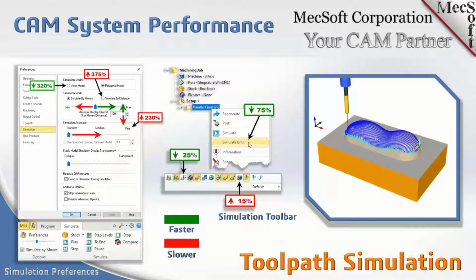You can think of a voxel model as nothing but a volume model that we create of a part file or a stock file, and that's what we use for simulation. The voxel model has restrictions because it's dependent on the orientation of the tool. For all 3-axis and 2.5-axis, as Don mentioned, you can use the voxel model.